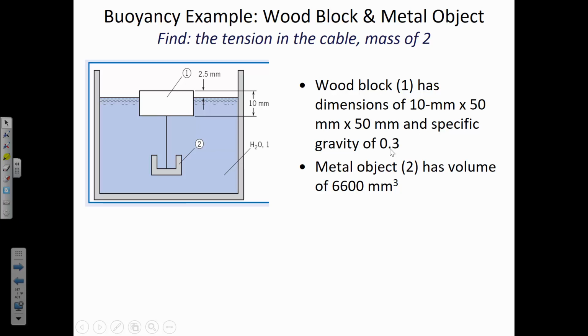So we're just bypassing that concern entirely, the difference between above and beneath, the weight of the water. So F sub B takes that into account for us. Is there another question? All right, so our force balance is going to be the weight of the object down, W2, is equal to T plus F sub B2.